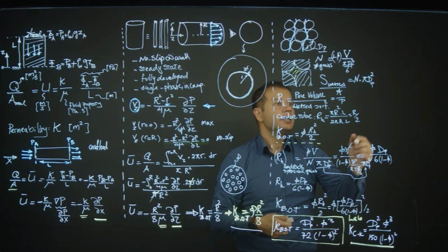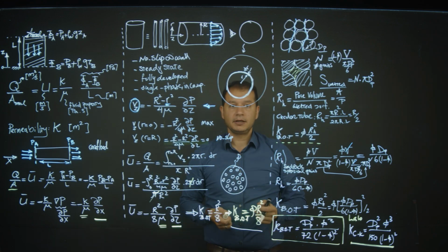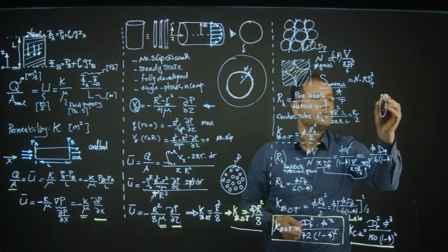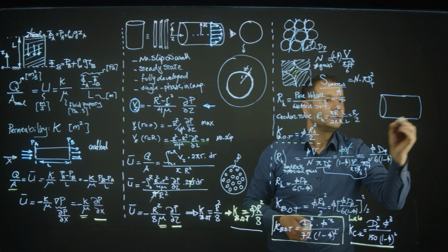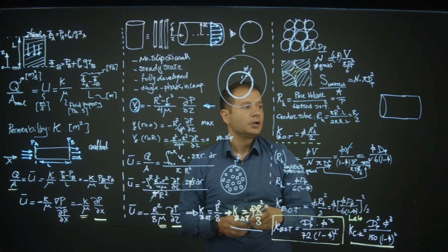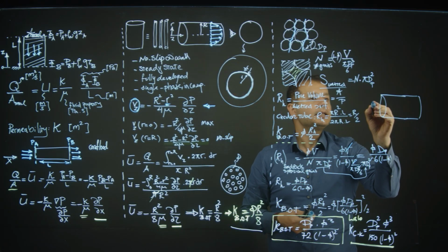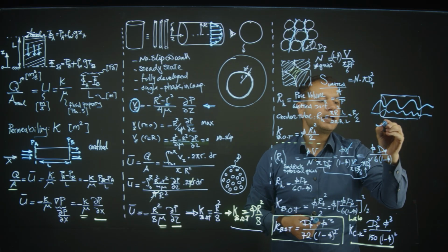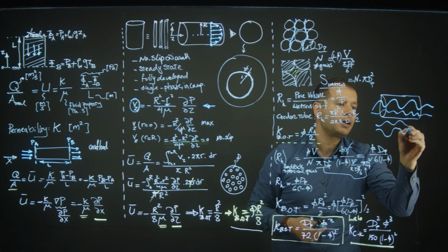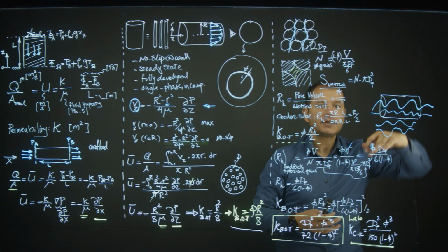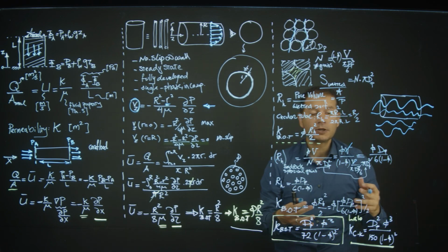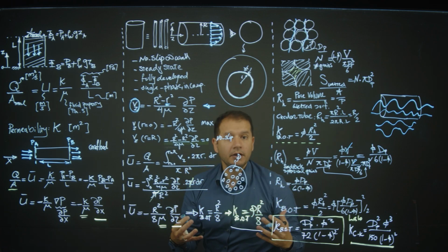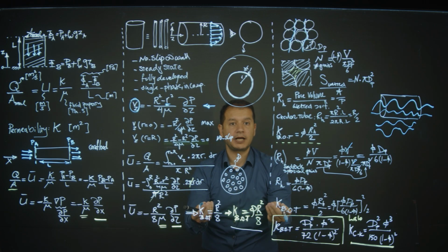The reality is that we assume that our tubes are straight, so flow happens straight. But in real rocks, in porous systems, flow does not happen like a straight line. It happens very much twisted. We have sudden expansion and contraction in pore geometries, we have twists, change of direction that cause additional friction. So permeability will be seen much smaller in real life than your straight tube assumption that we made in bundle